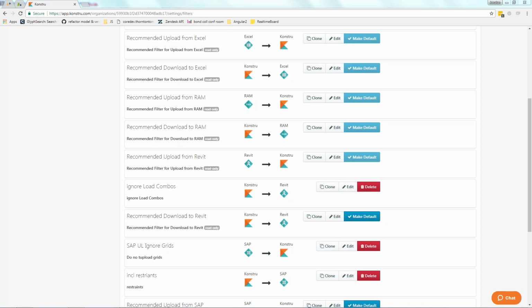On RAM, it's a bit different because RAM loads have their own geometry. So in this case, they won't be updated, so you would have to adjust them. We could also consider a way of pulling them back, but in RAM, we don't really have the information what element they're belonging to. So that's a bit tricky. But yes, to answer that, for CSI, you don't have to worry much about it.